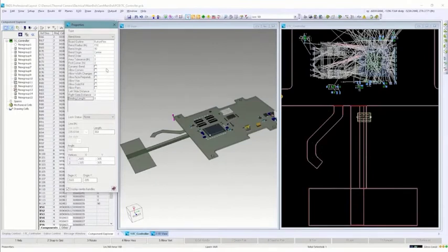And we're going to play around with a couple of these. It automatically identified that it was going to associate itself to the button Flex because those are the two edges of the Flex that it crossed over. It's got some default numbers in there, but we're going to adjust those. The bend origin just determines where the bend is going to occur relative to the shape. Bend order, is it being used currently?